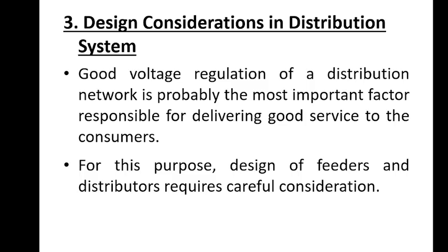To achieve this, careful design of both feeders and the distributors is essential, and feeders must be sized appropriately to carry the expected load without excessive voltage drop, while distributors should be designed to ensure uniform voltage levels across all points of consumption.